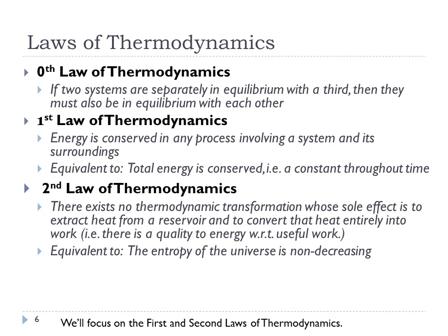That means the entropy of any isolated, adiabatic control volume will either increase, or eventually when it hits equilibrium, the entropy will stay constant from there on out. So the entropy will increase until it reaches equilibrium and then just flatlines, because once you hit equilibrium, you're at the state of highest entropy.